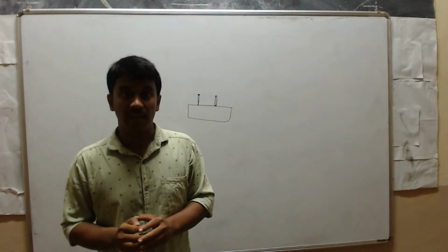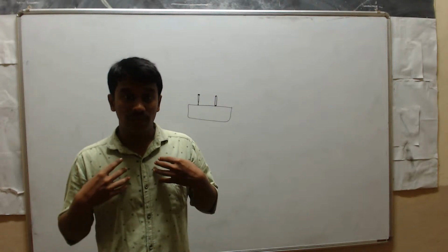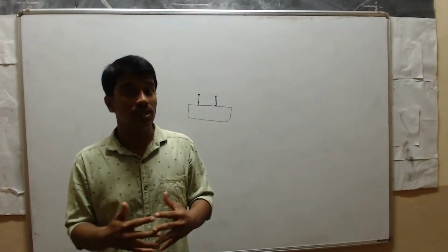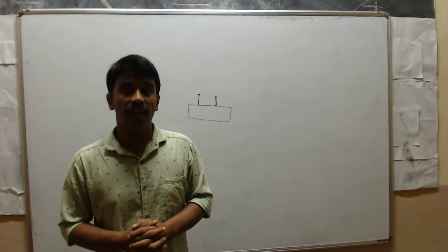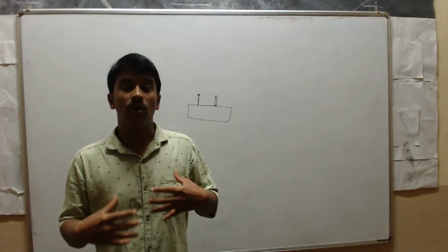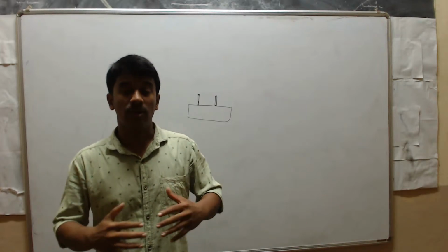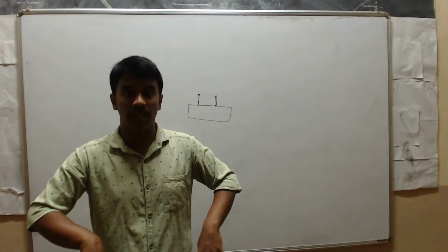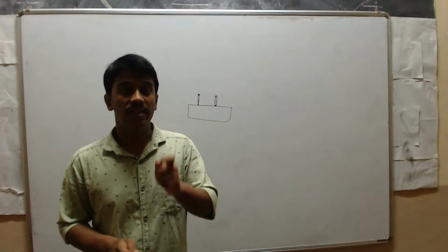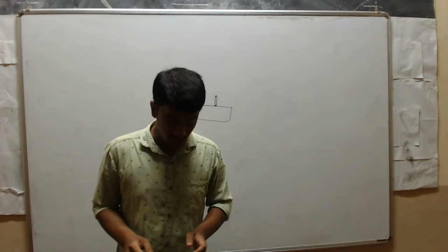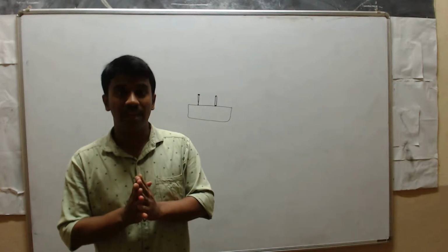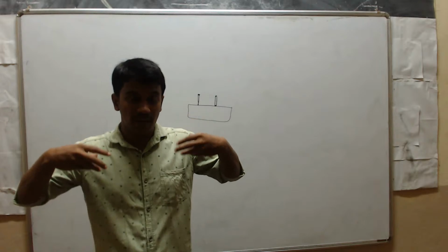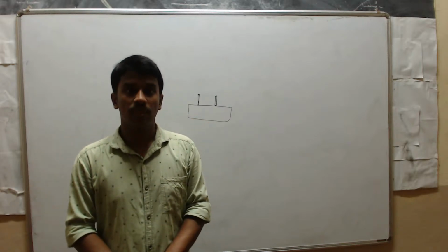When you sit, the force from your body is equal to when you stand. But when you sit on the sand, your body will cover more area. That pressure is distributed over that area. But when you stand, only your feet cover a smaller amount of area, correct? So the entire force from your body moves through your feet, right?